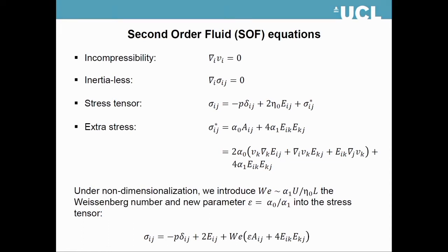Yeah, and easy. So I guess my question was then, what's the effect of the particles on the ratio of the normal stresses, or do they stay the same as the background fluid? They don't. It becomes a little bit more complicated, and there's a change of sign of second normal stress difference, which is interesting, but I haven't quite got my hand around it, so I haven't presented it. Because I think that fits with what happens in experiments. And I think experimentally, if you add particles, you change the second normal stress difference sign. So it does look like your theory is doing some nice effects. That would be highly useful. Thank you.